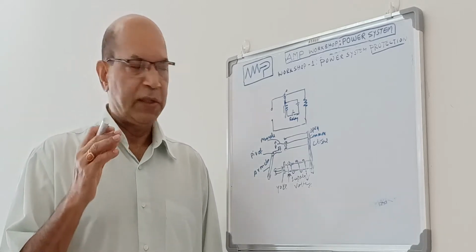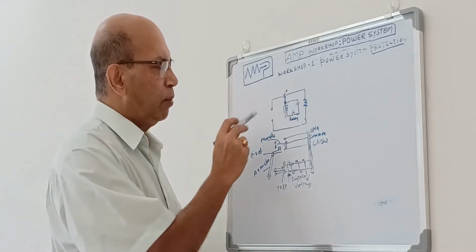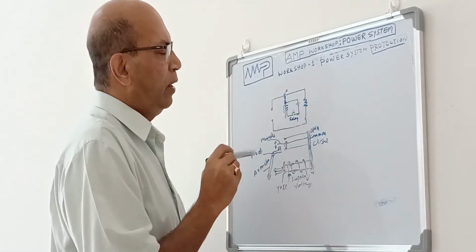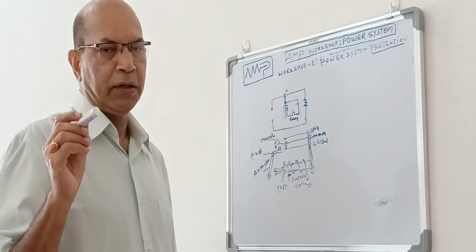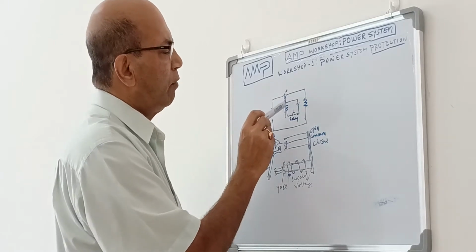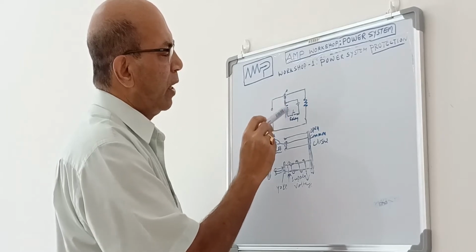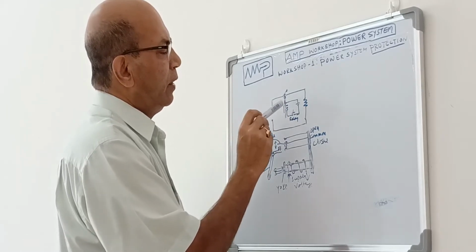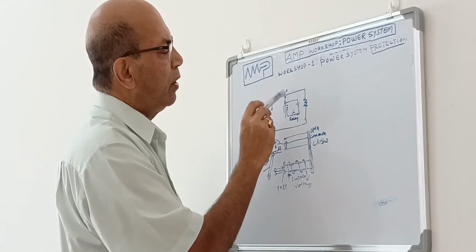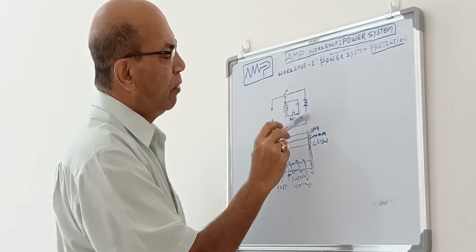So let us explain. I am explaining this relay with a small electromagnetic version. This is a small relay circuit we have drawn over here. This is the relay, an electromagnetic relay. Basically, an electromagnetic relay works on the principle of electromagnetic attraction or induction. Here, this is a solenoid connected with an armature. Now, when this solenoid is energized, immediately a magnetic field is produced perpendicular to the direction of current. Then this magnetic field will pull the armature, a magnetic material, downward, and immediately this contact will make. Then this is the main power source, and the power will go through this device.